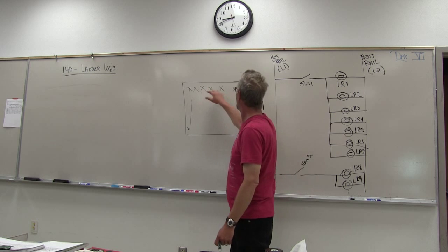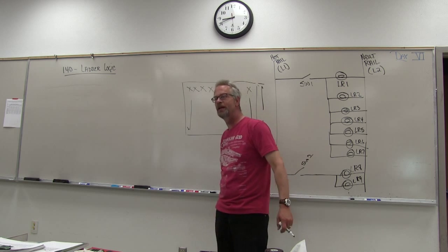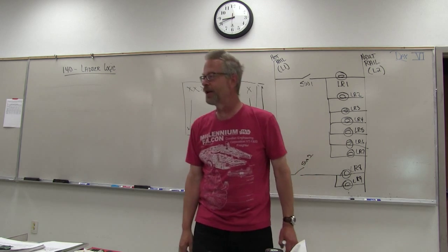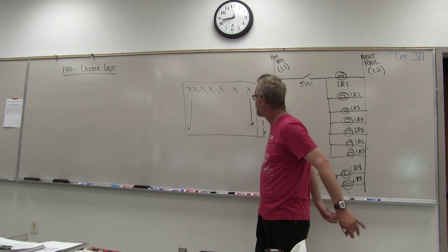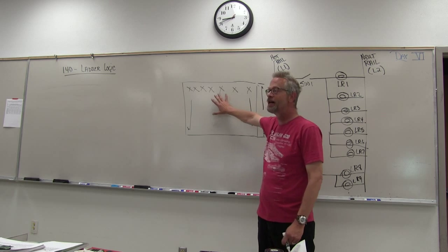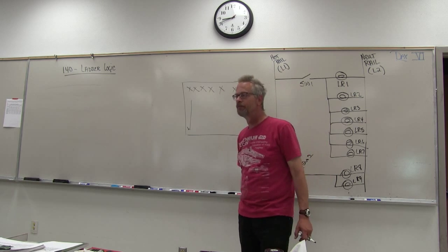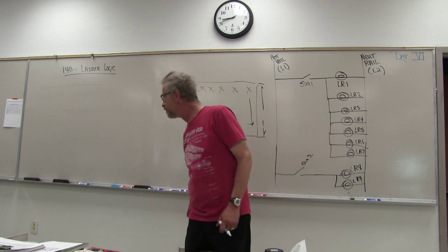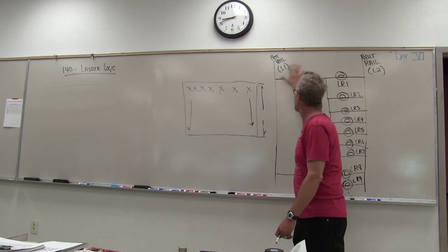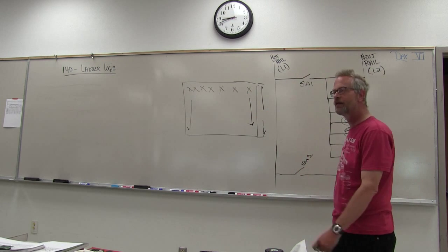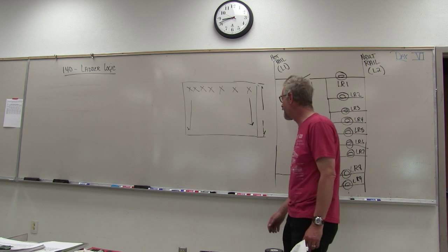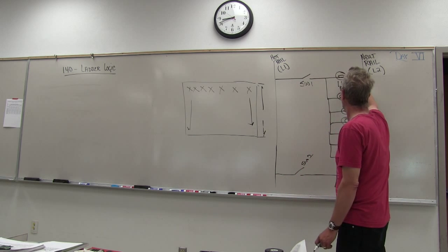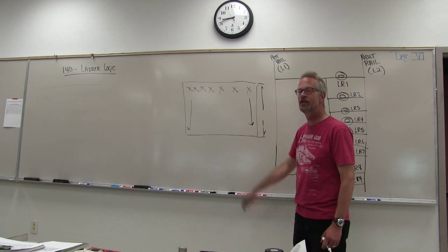They'll all be labeled. What's wired to which switch will be indicated in terms of the physical layout or the assembly or the elevation, whatever you want to refer to it as, of that room. You can see all of the positions. This simply details the electrical hookup without any regard for placement. There's got to be another document that says physically, where is that light, where is that switch?